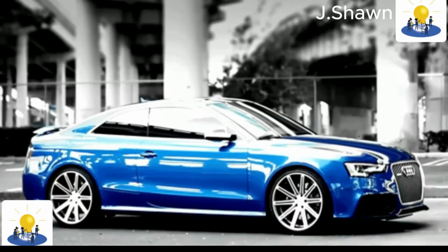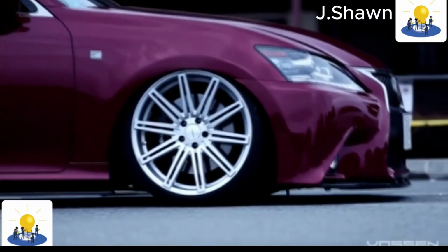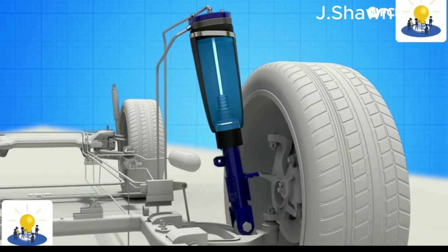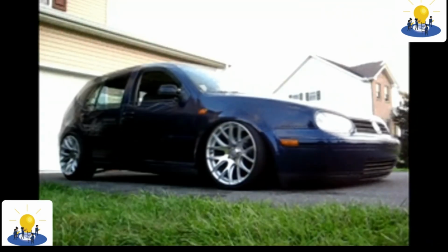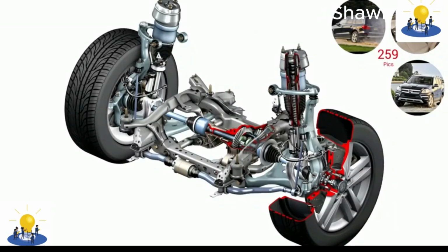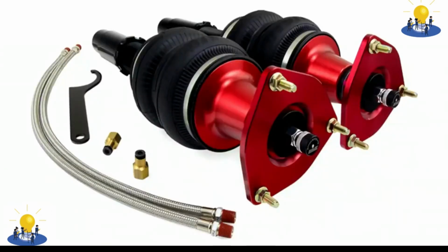It is important that the tank is sized for the task and can be calculated using a specific formula involving the compressor output, standard atmospheric pressure, and compressed pressure. High-pressure industrial gas bottles, such as nitrogen or carbon dioxide tanks used to store shielding gases for welding, are sometimes used in more radical air suspension setups. Either of these reservoir systems may be fully adjustable, being able to adjust each wheel's air pressure individually. This allows the user to tilt the vehicle side to side, front to back, in some instances hit a three-wheel motion, contort the vehicle so one wheel lifts up from the ground, or even hop the entire vehicle into the air.